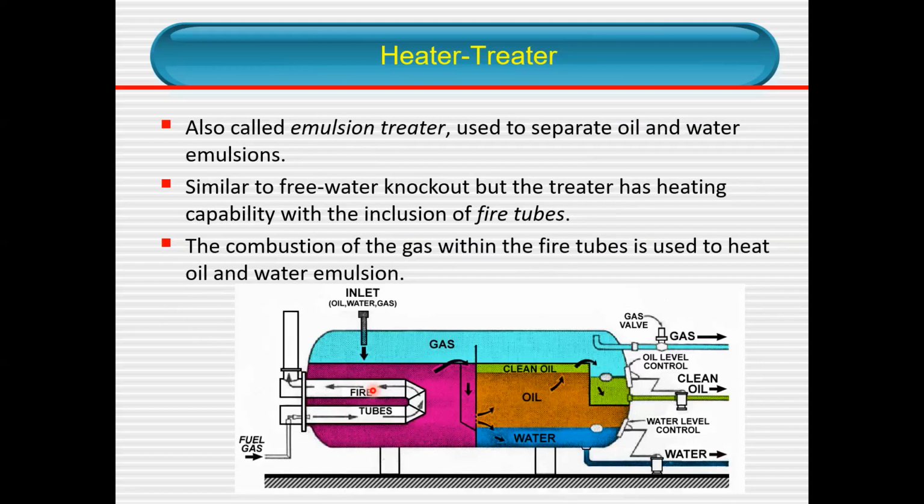But as you can see here, we hope we don't have this kind of emulsified fluid, because the heater treater is more expensive. To optimize the cost, we see whether we need this heater treater, or whether we can just make use of chemicals to de-emulsify the emulsified fluid. So any emulsion, you have to have this. If not, try to use a normal separator but with some chemicals, so that you have clean water.